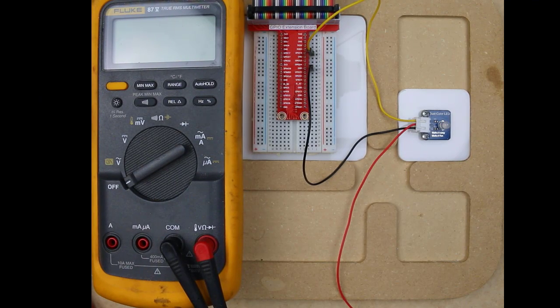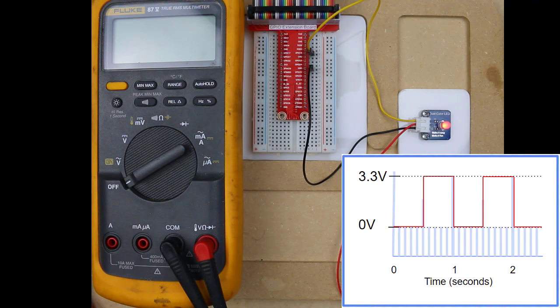Here we can see the LED is blinking. Your LED should be blinking at a frequency of 1, meaning 1 cycle per second. So you should see it go off and then on in a 1 second period of time. A half a second it is off, and a half a second it is on. The duty cycle for this is 50%, meaning that half of the cycle the signal is in the on position.